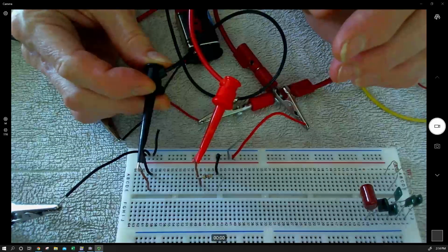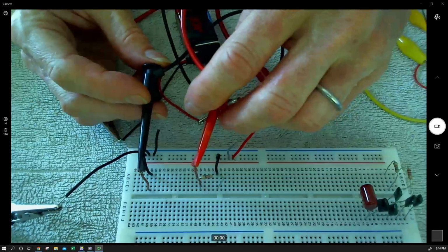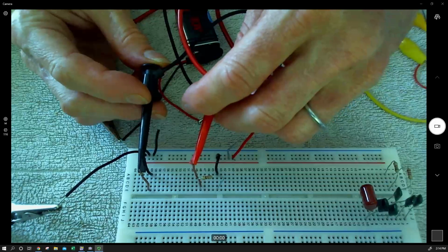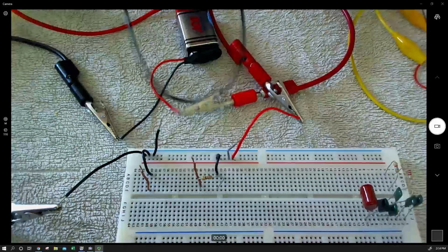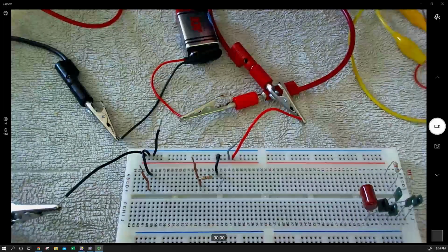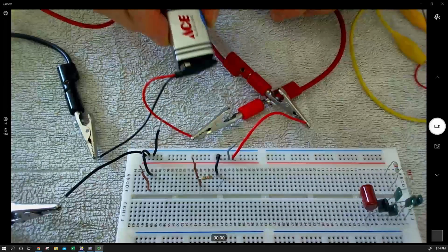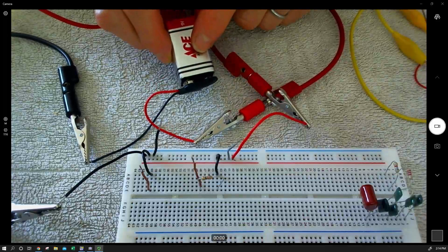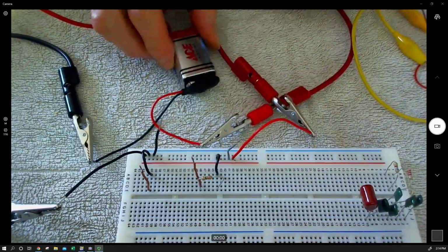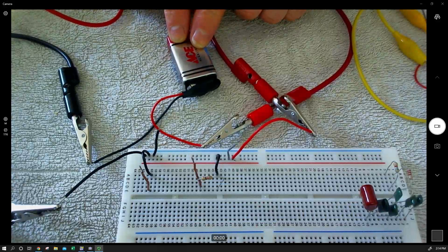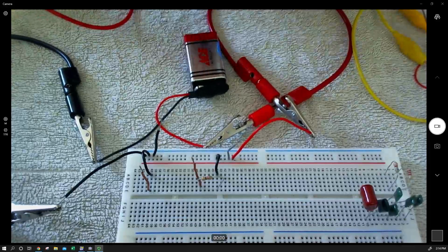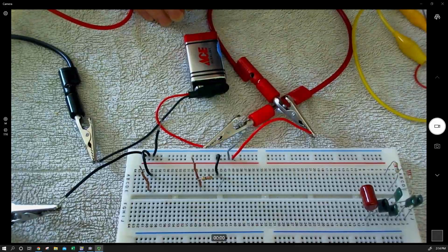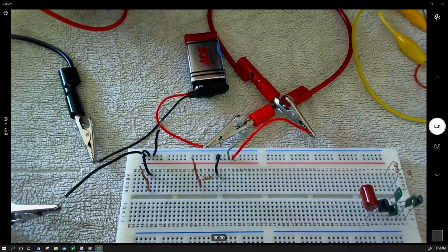Okay, so I'm connecting, and my meter is reading about 94 milliamps, and 93.6, 93.5, and it's dropping quickly. That fairly fast reduction is indicative that we are being affected by the increasing internal resistance of our source. And that is very characteristic of an electrochemical source that is depleting, especially alkaline type batteries, the small primaries. So we'll just round that off. We'll say that was approximately 94 milliamps and dropping quickly.